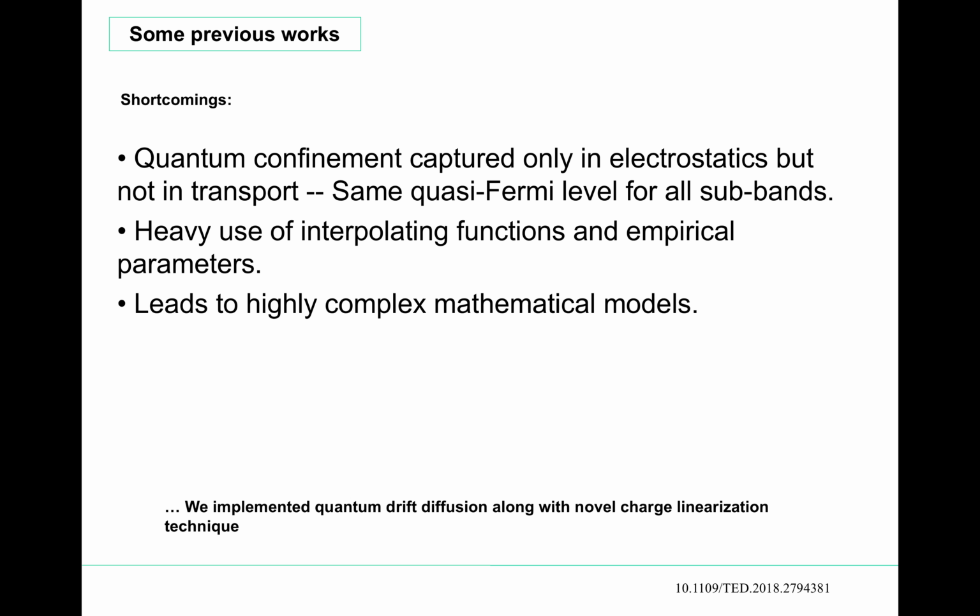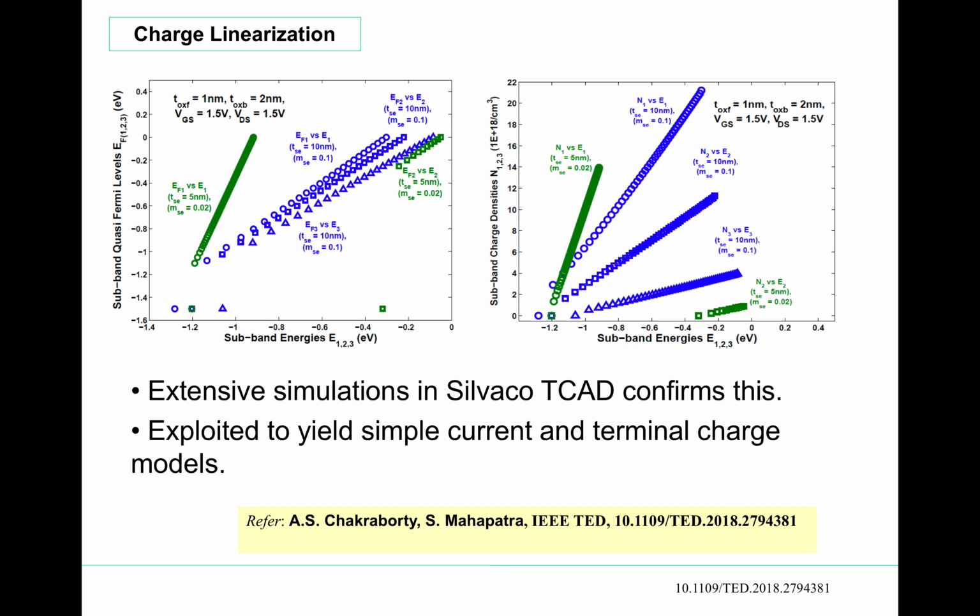So in our case, we implemented quantum drift diffusion along with a novel charge linearization scheme that gave us a very simple transport model that we have discussed in detail in our paper, and we will briefly describe it in this slide. This is the charge linearization.